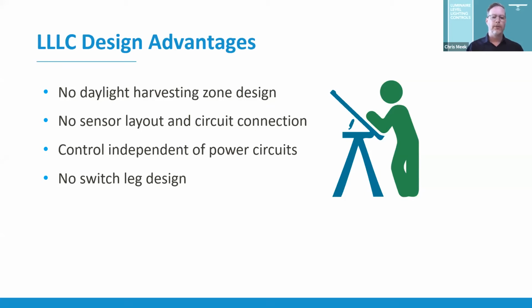They respond to those changes, whether throughout the day for daylight, or if they paint the space and there are new reflectances, or there's a new furniture layout, or as the patterns of daylight change across the year. Since the fixtures are granular, they just change as they need to for each sensor location. A designer or an engineer doesn't have to identify the location of a single sensor for a zone that has to stand in as representative of the space, because a single location really can't represent all the changes that happen within a space during the day in terms of vacancy, daylight, and occupancy. So you don't have to commit to one location. The control zone just happens naturally because each fixture is operating independently.